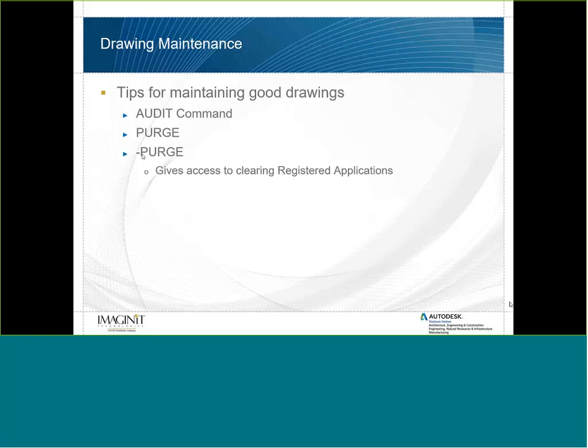You purge them out, and the drawing performance changes dramatically. Instead of being glitchy and choppy, all of a sudden after you've done that save, after you've purged those registered applications, when you click on things, you get the performance back that you expect.